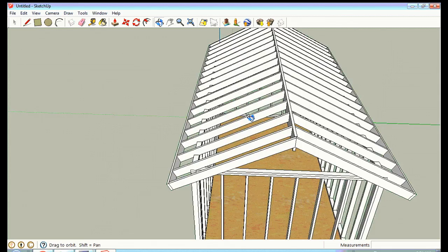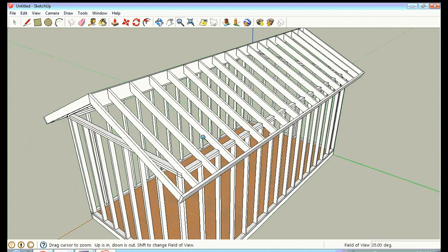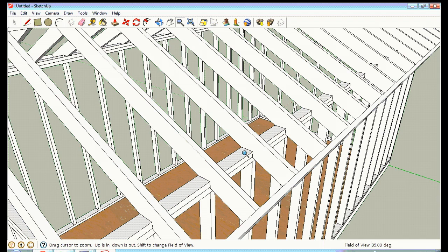So that's much quicker. Now you will notice that the roof style design uses what is called a traditional bird's mouth construction method. Each of these 2x6s comes down from the roof beam, and then they have a notch cut in them that's called a bird's mouth. Each bird's mouth sits directly on the top plate of the wall. And this is a very strong traditional building method still used in most new structures. However, the new building methods, and especially a lot of codes, require that you also use a hurricane strap, which is a metal strap that goes on the inside of the sill plate and then connects right here to the wall.